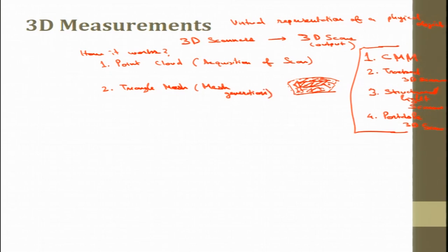The third step, when the mesh is generated, is that we need to optimize the mesh. When we conduct a strength analysis or heat analysis on this mesh, the more triangles there are, the more computation is needed. So it depends upon what type of computation we need to do. So we optimize the mesh to reduce the computation time and to get the optimum shape as well.